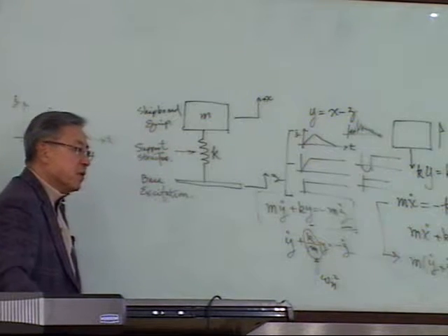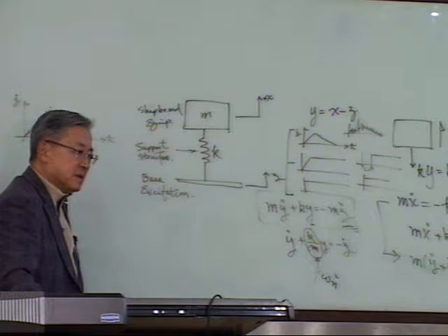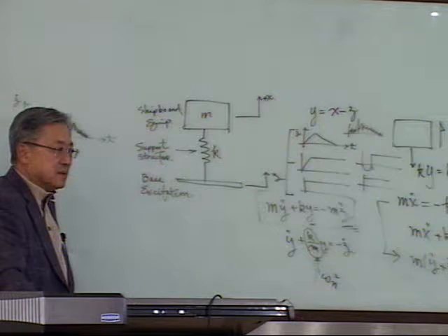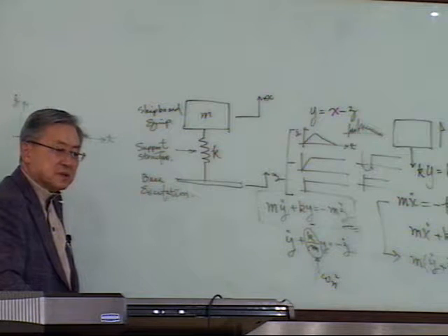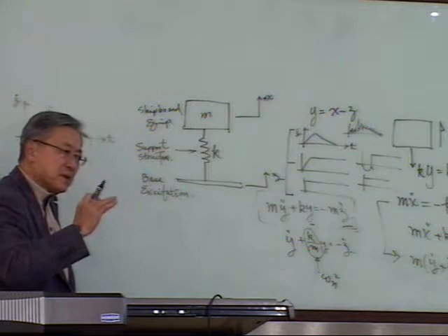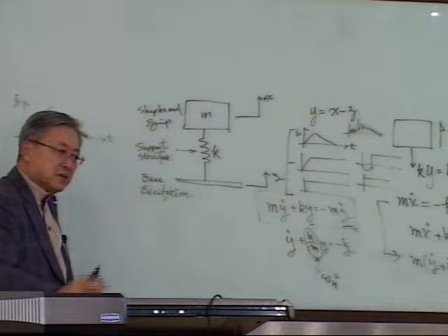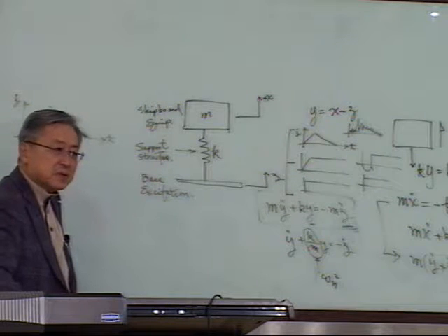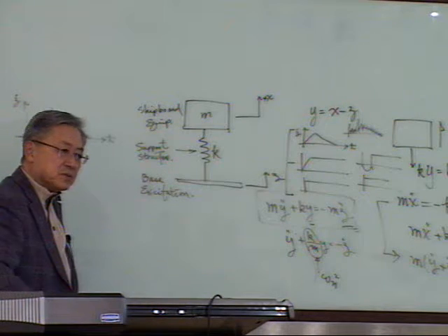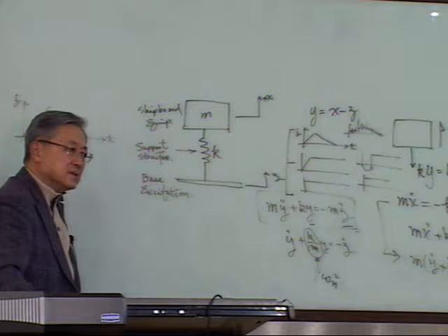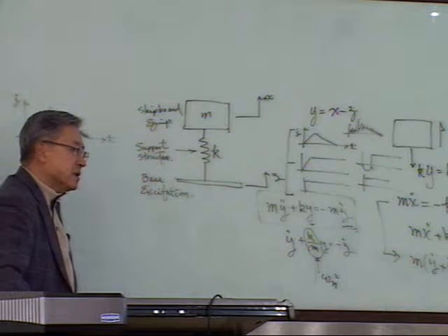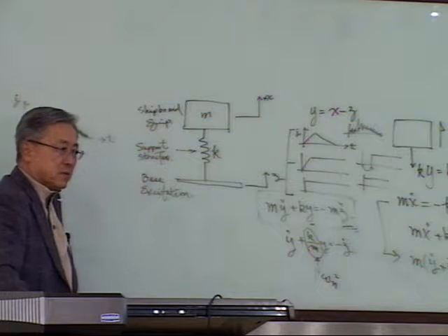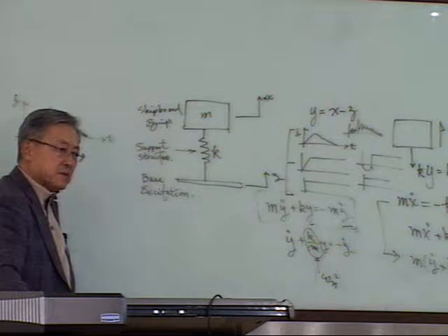Maybe 20 hertz, maybe 10 hertz, maybe highest, maybe 30 hertz. What does it mean, important? The natural frequency, which can resonate with excitation frequency, is in the range of about 20 to 30 hertz, sometimes below, okay? So you don't have to worry much about the above 50 hertz range for equipment design, always low.